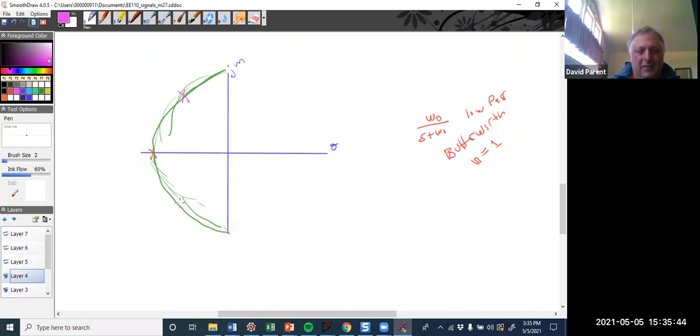All right. Well, what if I wanted a second order Butterworth filter? Well, the radius is 1, right? So I'm getting, S plus 1, no, sorry, 0.707 plus 0.707 j. That's one pole. And then I get its complex conjugate.